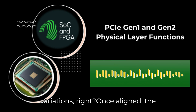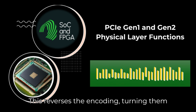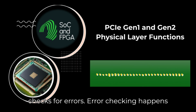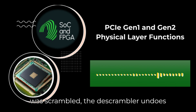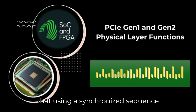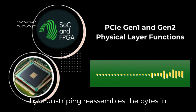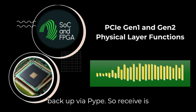Right. Once aligned, the 10-bit symbols go to the 8B10B decoder. This reverses the encoding, turning them back into 8-bit data or K symbols, and it checks for errors. Error checking happens here too. Basic checks, yeah. Then, if it was scrambled, the descrambler undoes that using a synchronized sequence generator. And finally, if multi-lane, byte unstriping reassembles the bytes in order before sending the parallel data back up via PCIe.